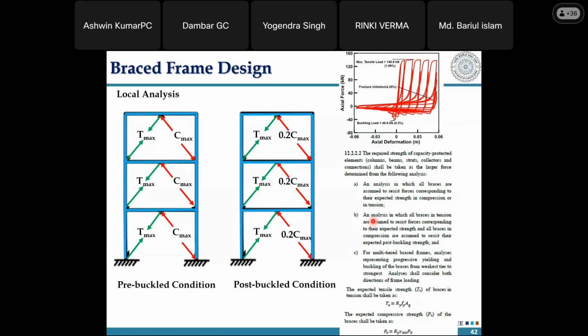But there are two points that I want to mention. Every time you design a structure, kindly give both earthquake and wind load combinations. If wind is totally governing your design, then there is no local, global, or any such analysis coming into the picture. The brace will not undergo any nonlinear yielding or buckling. It will be just elastic overall throughout. So there is nothing to be seen in this particular case. If seismic is governing, then this procedure will come into the picture.